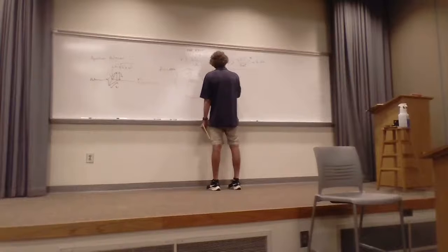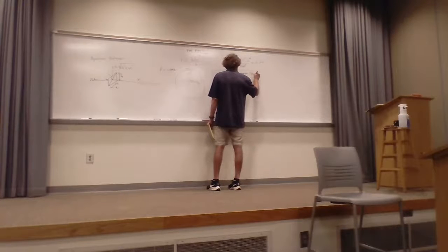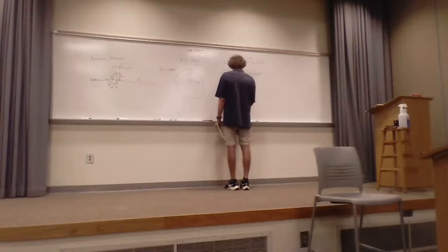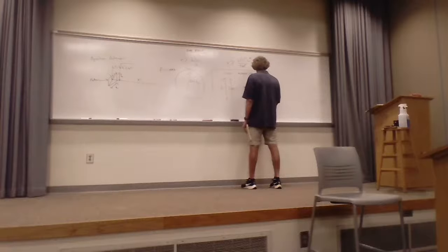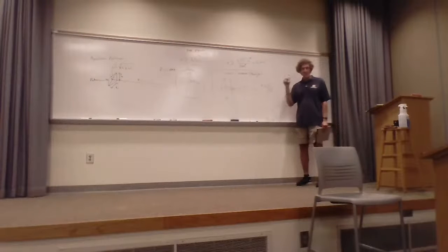For a straight wire antenna of length L, the distance you have to be greater than to be in the far field is R simply greater than lambda over 2 pi, which is completely different, because then as wavelength goes up, you can be closer and closer. We'll prove that one, all right? Not right now, but we will.